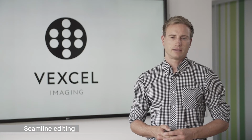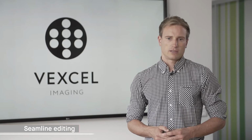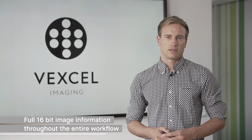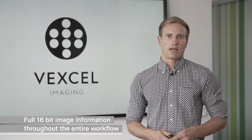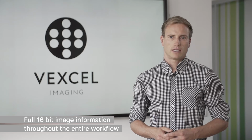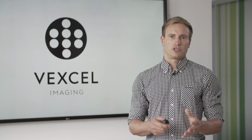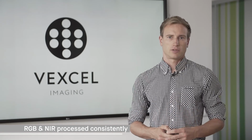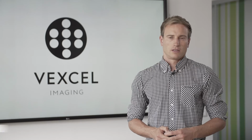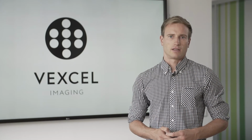Of course, UltraMap also includes tools for seamline editing, and we are using all our images with full 16-bit in this workflow. So all image information is available until the final end product, and along with that we are also processing the RGB and the near-infrared channel, always in parallel, always consistent processing for all 4 bands, so that the full data quality is available until the final product.